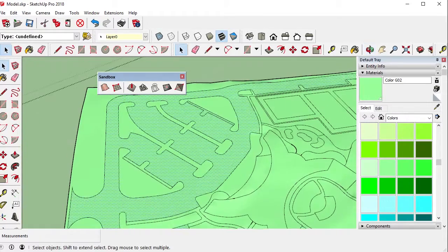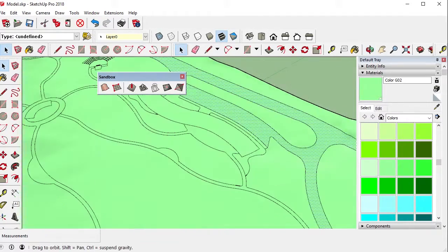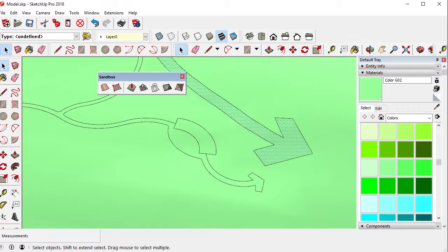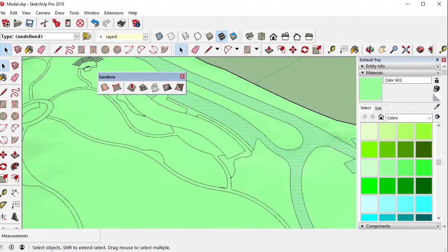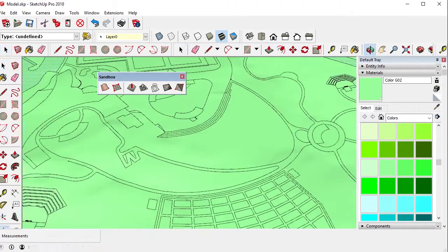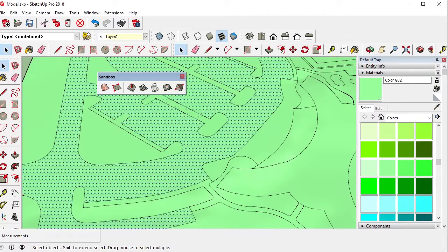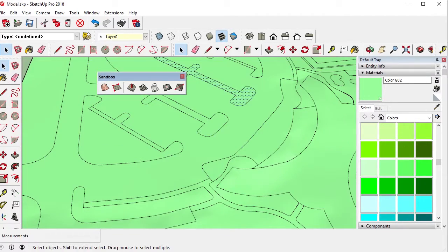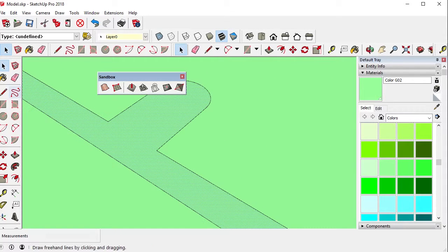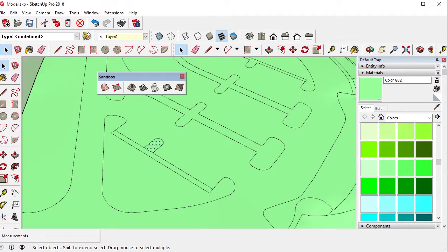And so it looks like I'm only getting my paved area here. It comes through. Those arrows are not paved areas, but that's what the CAD file had. So I'm going to just use that as my material change. I also have islands in here. So again, for the interest of time, I'm going to use this area here. This is probably not, the entire thing is not a walkway. So we'll separate those two areas.